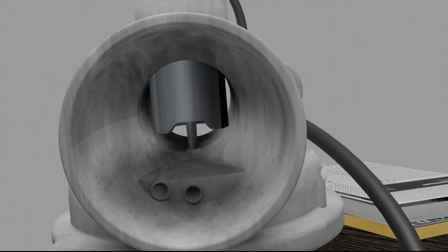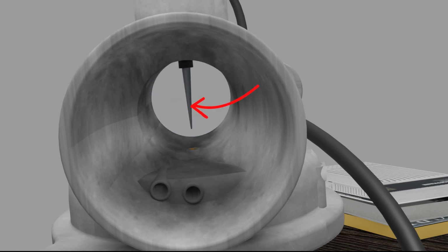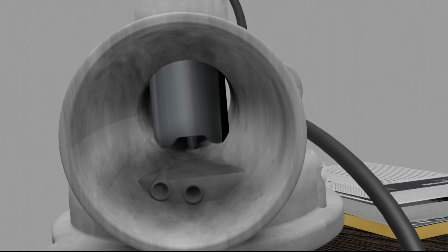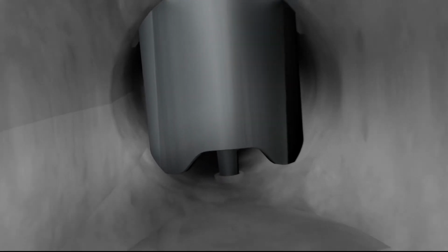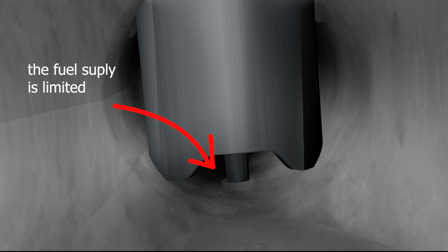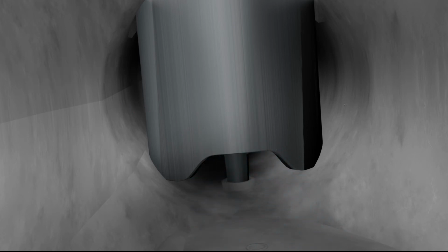When the piston is at the bottom, the intake pipe becomes narrower. And if you look, this piston is installed with a pointed needle. So in the bottom position, the needle will close a bigger part of the main jet. It aims to avoid oversupply of fuel, because in a thin channel, air passes faster even though the total mass passed is small. The pointed needle makes sure that the sucked fuel is not too rich.